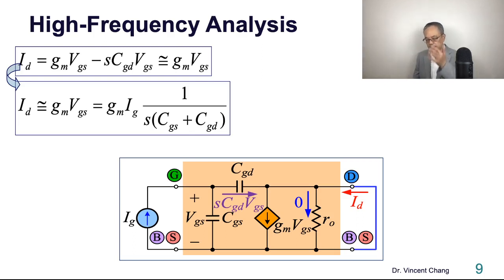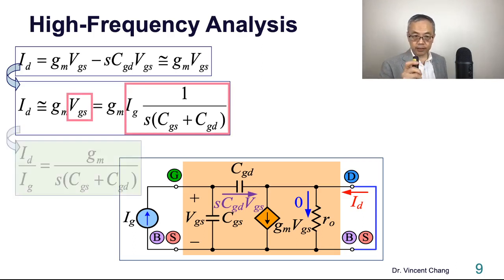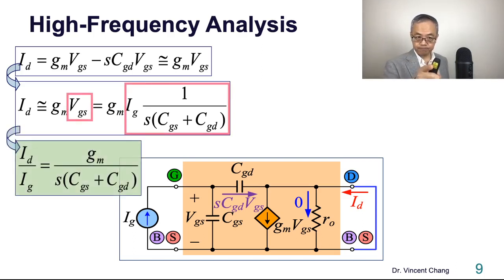So it's the parallel combination between the two capacitances, all right? So the current times the impedance. The impedance is 1 over S capacitance, and the parallel capacitance is just the sum of the individual two. All right? So then you got this, the left-hand side of your slide.